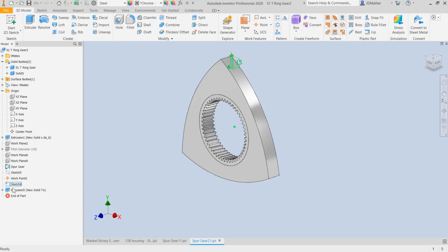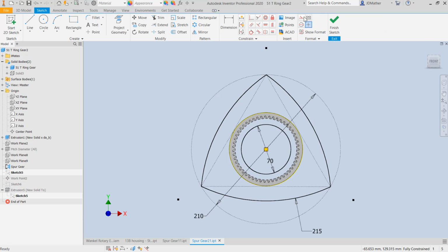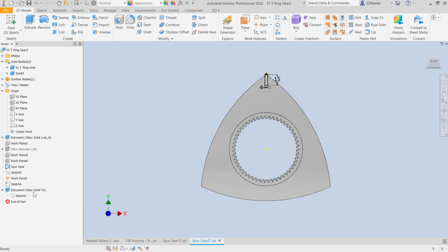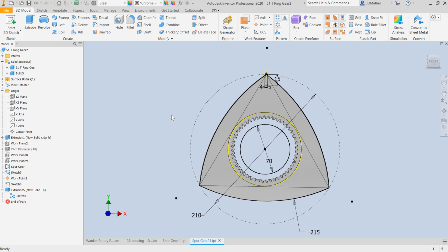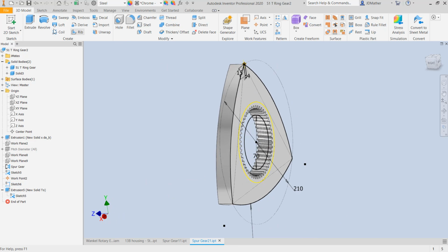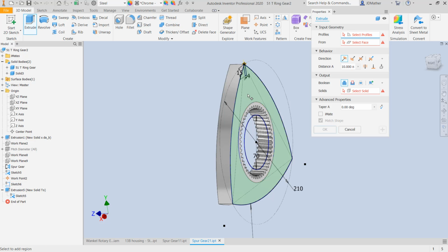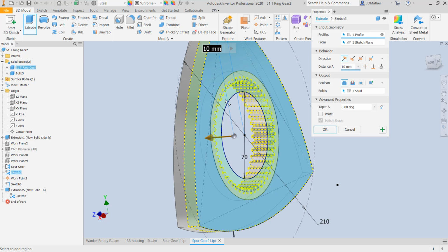I will make the previous sketch visible again, and I did edit sketch. I want to just make that visible, so I'll right click, turn on the visibility, and then I'll do extrude again, and this time I'm going to select both the triangular area and this area.